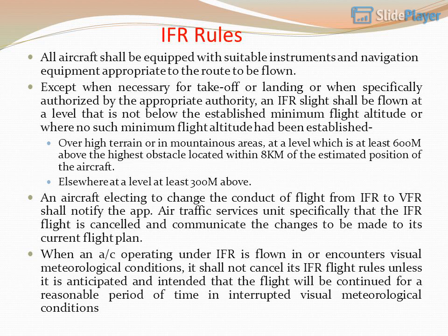An aircraft electing to change the conduct of flight from IFR to VFR shall notify the Air Traffic Services Unit specifically that the IFR flight is cancelled and communicate the changes to be made to its current flight plan. When an aircraft operating under IFR is flown in or encounters visual meteorological conditions, it shall not cancel its IFR flight rules unless it is anticipated and intended that the flight will be continued for a reasonable period of time in uninterrupted visual meteorological conditions.